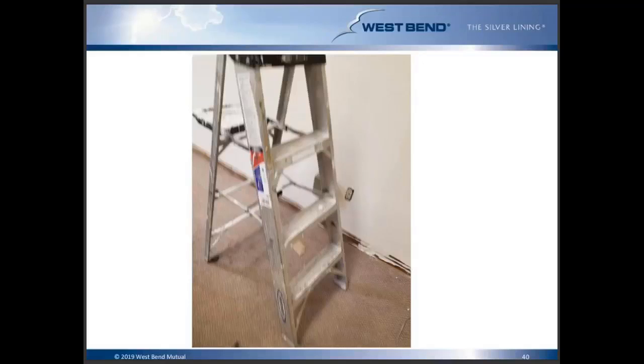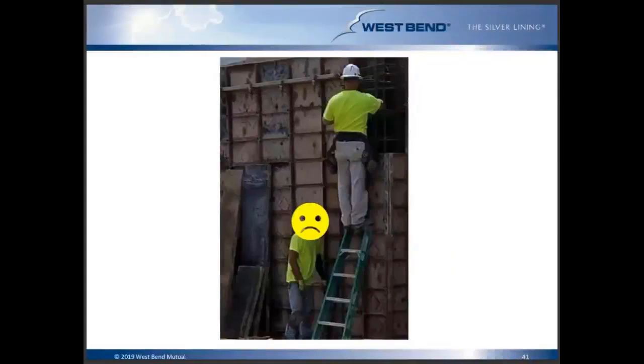The other reason I wanted to mention this is the electrical shock: if we did have somebody that was shocked by using this ladder and being so close to a conductor, the actual shock might not hurt them. It could likely be the fall from that ladder that could seriously injure them, or in some cases result in a fatality. So again, just another reason why choosing the right ladder can help you prevent a serious injury.